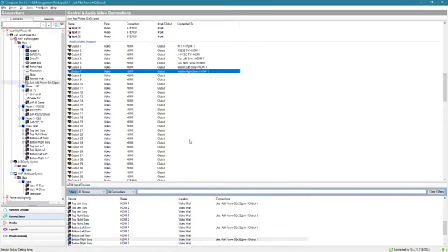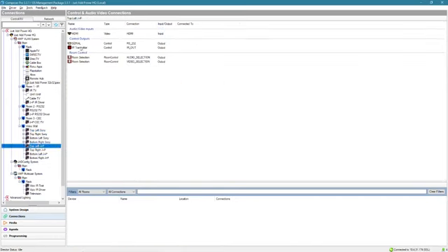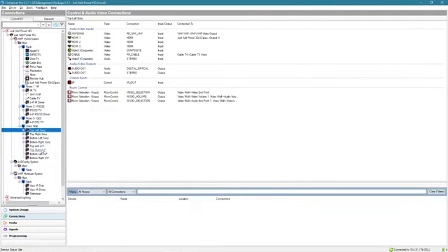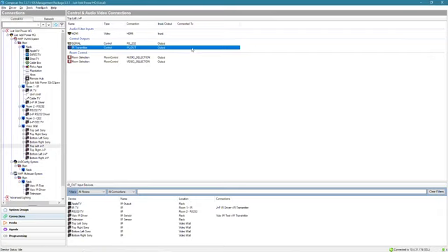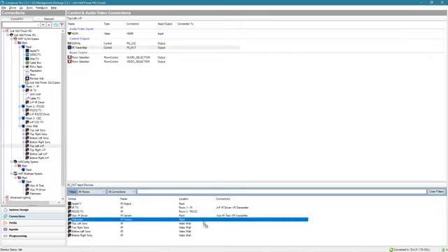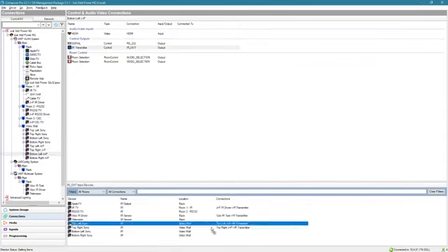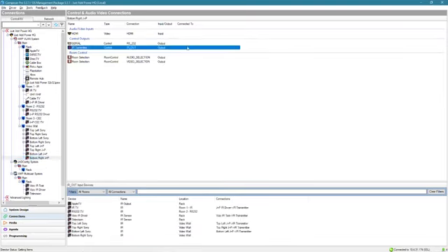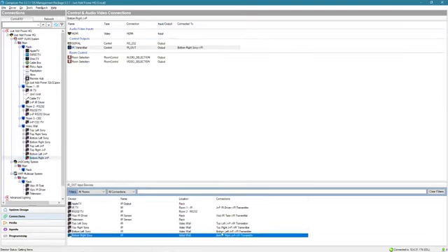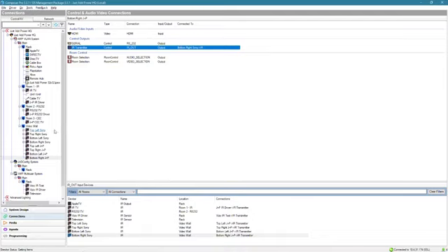Remember, we're connecting the television itself, not the Just Add Power driver, because we want to be controlling the actual television when we do switching. So our drivers are configured. If we were doing IR as well, we would connect IR, but these TVs seem to be IP. Oh no, they're IR. IR, so we'll connect those as well. Top left to top left Sony. Top right to top right Sony. Bottom left to bottom left Sony. Bottom right to bottom right Sony. That's not part of the video wall. That's just because they're IR TVs. You probably want to control them as well.